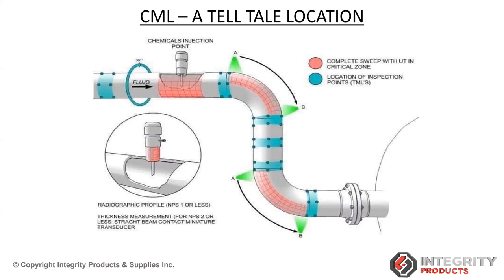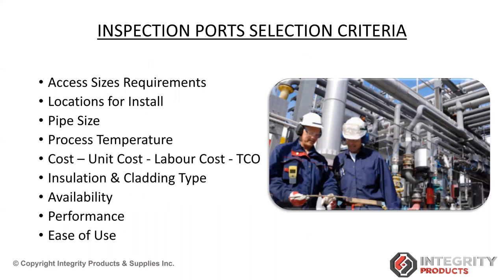So filming inhibitors, what they do is build a protective or passive layer on the inner surface of the pipe. Whenever they are injecting the inhibitors, accordingly the corrosion rate on the pipe could be minimized, and that reduced corrosion rate has to be monitored from the external surface of the pipe via CMLs. So that's why it's very important for process optimization.